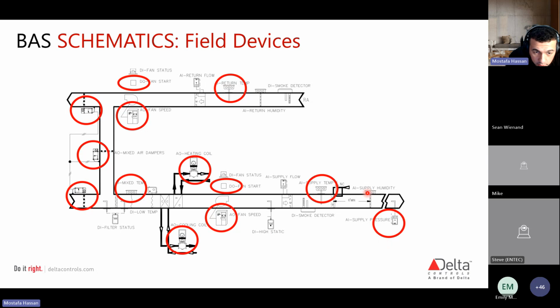Maybe later on, if the pressure reaches this value, you can get the actual value, right? Because this is a supply pressure sensor, so it's going to collect the actual value. But over here, we don't care. We just want to know if it's triggered. And that's why it's digital, right? On, off. Did it trigger or did it not trigger? That's the difference between digital and pulling in the actual value via analog.